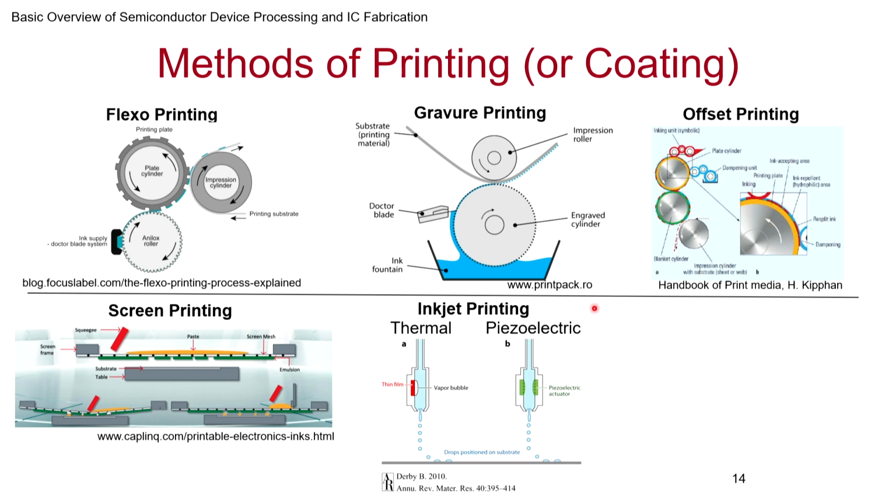And then you have inkjet printing. Originally they used to have continuous drops. They'll charge the drops and try to deflect whichever shouldn't go to the substrate. It will go to the drain. But more recently, since the time many of us have been using it in our offices or homes, there is something called bubble jet.